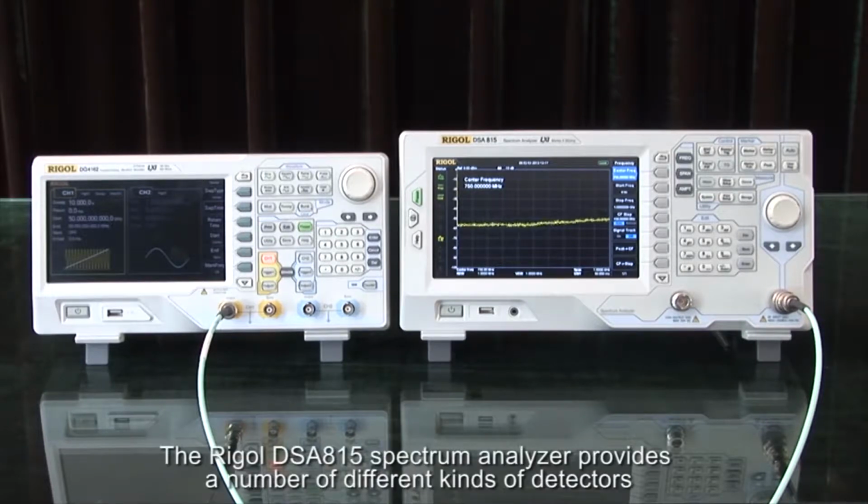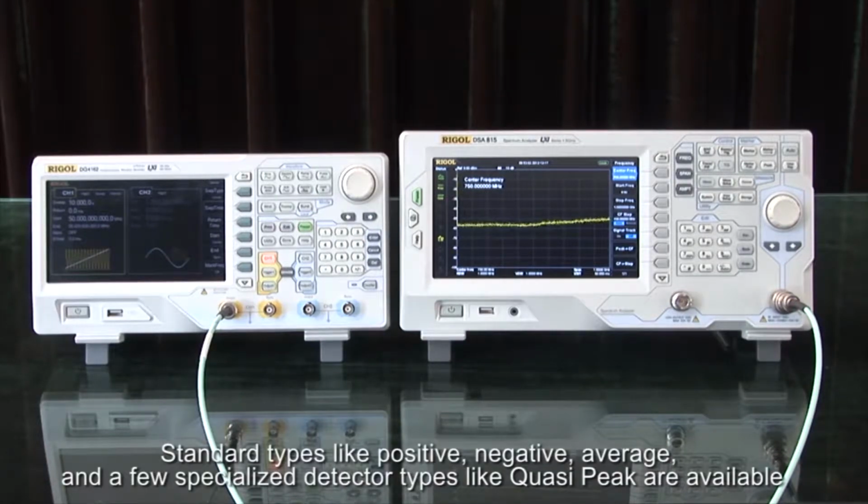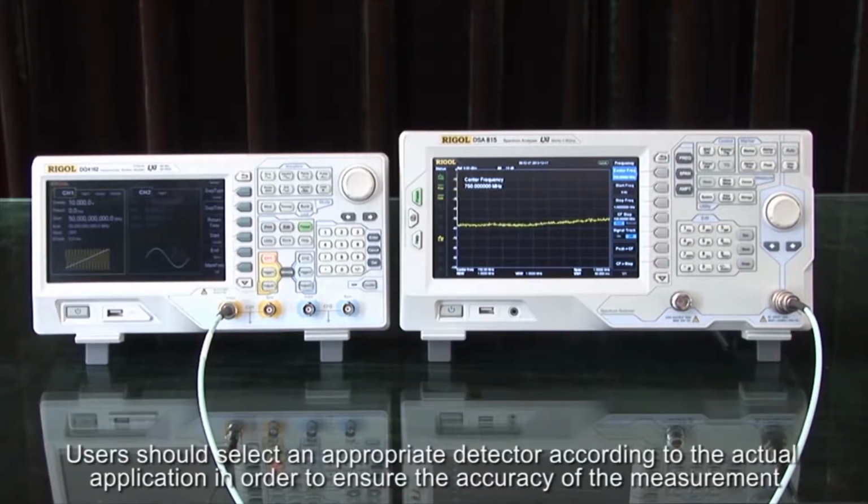The RIGOL DSA 815 spectrum analyzer provides a number of different kinds of detectors to help isolate and examine different signals. Standard types like positive, negative, average, and also a few specialized detector types like Quasi-peak are available. Users should select an appropriate detector according to the actual application in order to ensure the accuracy of their measurements.